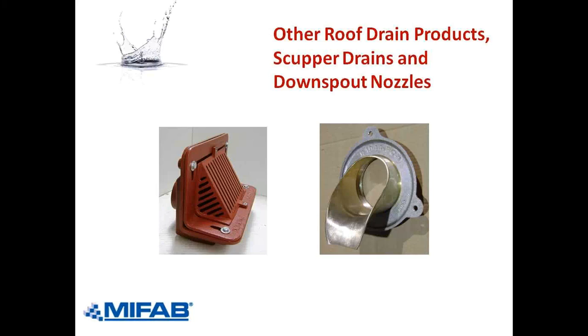A lot of you, next time you're at a hotel or an airport and you're in an elevated position, maybe on a train going to the terminal from the parking lot, look down at the buildings that go by underneath you, and look at the roof drains. You'll notice there's typically two roof drains side by side. That's because one is the primary, one is the secondary.